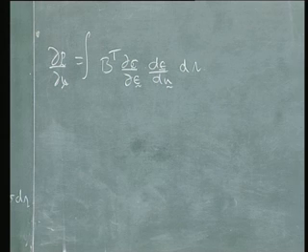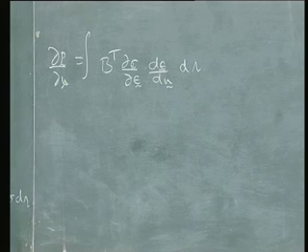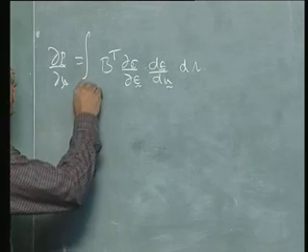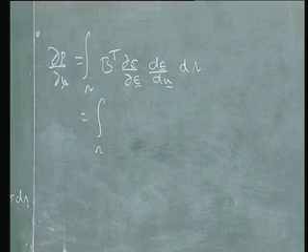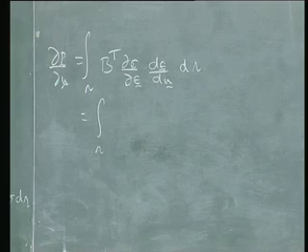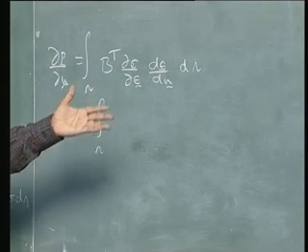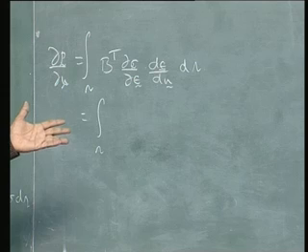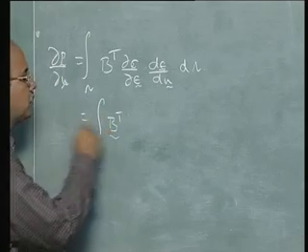So d sigma by d epsilon is nothing but the slope of the stress strain curve. People call this with different names. Suppose you are working with Abaqus, sometimes this is called Jacobian, or a small modification of this may be called Jacobian. Most important, this d sigma by d epsilon is the most important quantity that is useful in nonlinear finite elements. Note that in a linear finite element, this straight away reduces to your well known stress strain relationship, Hooke's law, and can be expressed in terms of E and nu and so on, isotropic elasticity.